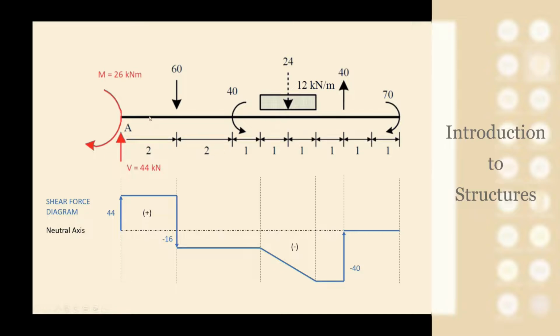because of the equilibrium, you cannot have in a cross section to the left a value and to the right another value. So it's not just constructing the shear force diagram, it's to be sure that you understand the definition of the shear force. That, remember, is a simple definition. The shear force at every cross section of a beam is the summation of shear forces to the left of the cross section, or the summation of the shear forces to the right of the cross section.